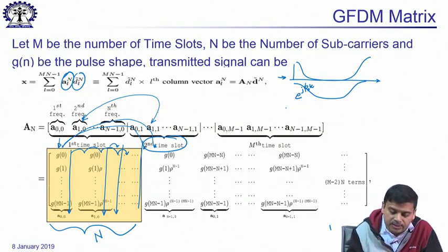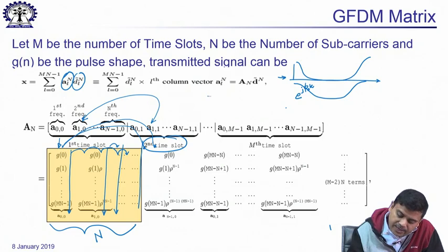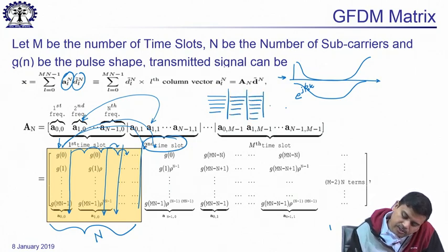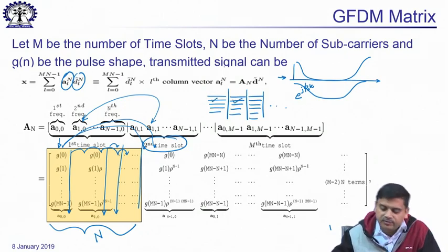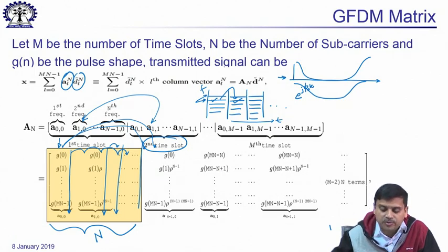So, between this and this, as has been pointed out, there is no difference in the frequency shift, that means they are the same subcarriers. In the time frequency diagram, if these indicate the first block, these the second block, these the third block, and so on, then this one and this one have the same frequency shift, but two different time shifts. This is the time axis, this is the frequency axis, whereas this and this have a frequency shift with respect to each other, but no time shift between them.